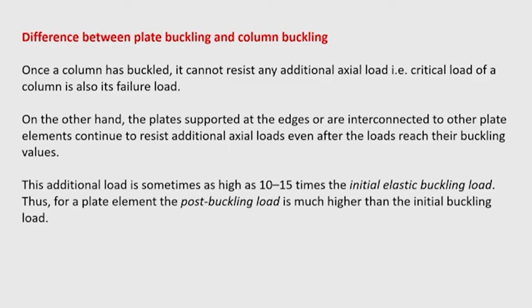So, this phenomenon is observed in case of plate. For example, a plate has dimensions which are important in both directions, say x and y direction. So, when the buckling takes place in case of line elements, a column that we have studied, we have seen that the bend shape that is formed is in the form of a single half wave that gives the lowest value of the buckling load, that is the critical load.